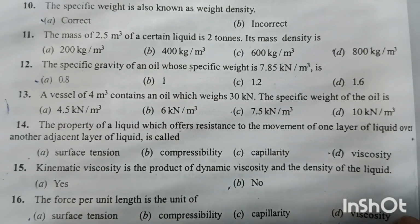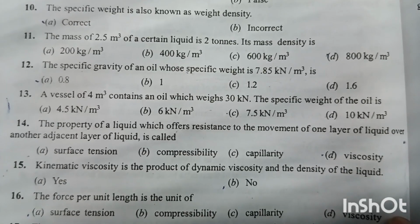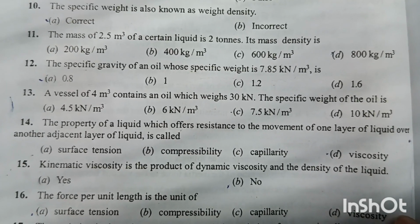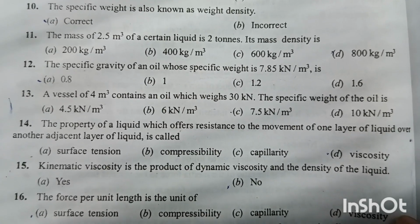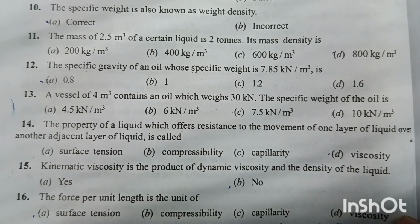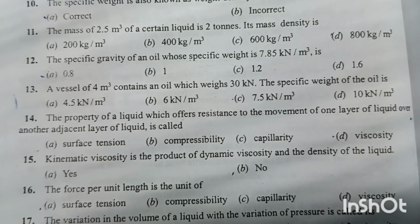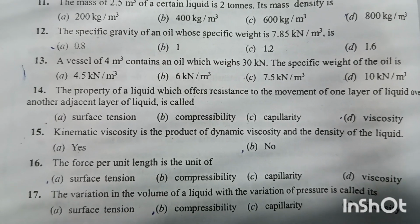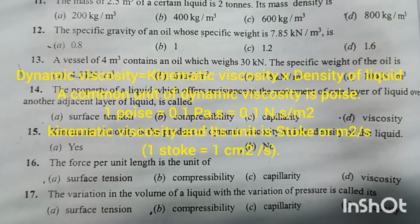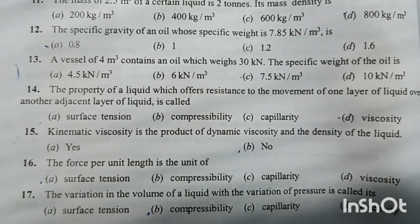Question number 14. The property of a liquid which offers resistance to the movement of one layer of liquid over another adjacent layer of liquid is called viscosity. Option D is right answer. The internal resistance between the fluid layers is known as viscosity. So option D is right answer. Question number 15. The kinematic viscosity is product of dynamic viscosity and density of the liquid. No. Dynamic viscosity is the product of kinematic viscosity and density of the liquid. So option B is the right answer.